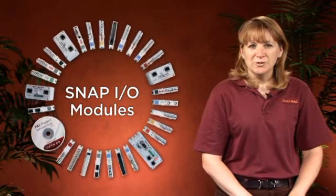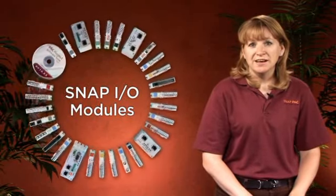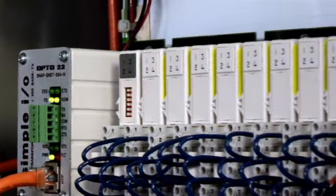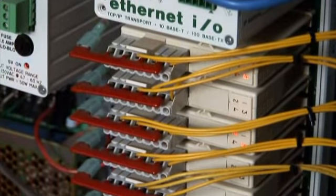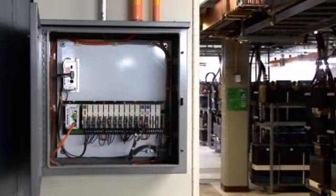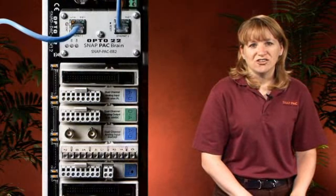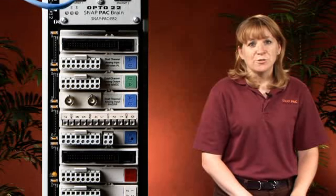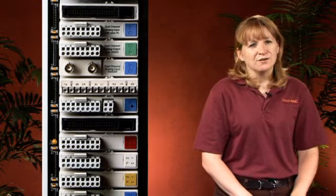Because Opto 22 has nearly 100 different SNAP I/O modules, we can handle just about any type of signal in your application. You choose the ones you need based on the sensors and devices you're controlling or monitoring. And because many are software configurable, a small number of modules can handle a wide range of tasks. SNAP modules are available in a variety of configurations, ranging from 1 to 32 channels per module. That way, you have the right amount and the right type of I/O for your application without having to buy more than you need.